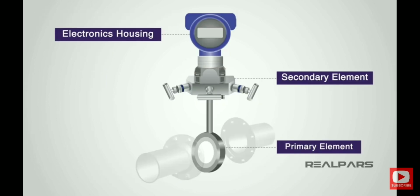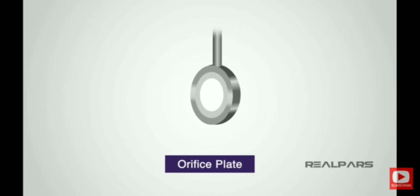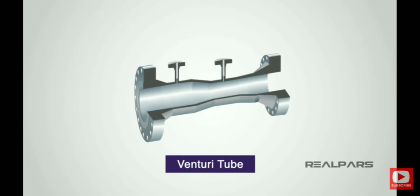Let's look at the working of a DP transmitter. A DP transmitter is a pressure measuring gauge or electrical device that uses two elements to measure a difference of pressure in a sealed container, such as a pipe. A DP transmitter will have a primary element, a secondary element, and an electrical housing. The primary element will produce a difference in the pressure as the flow in the pipe increases. Different types of primary elements include orifice plates, venturi tubes, flow nozzles, and averaging pitot elements.